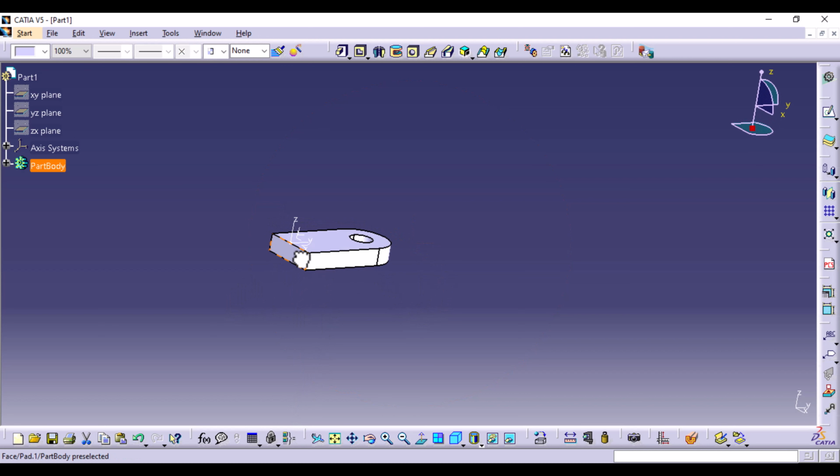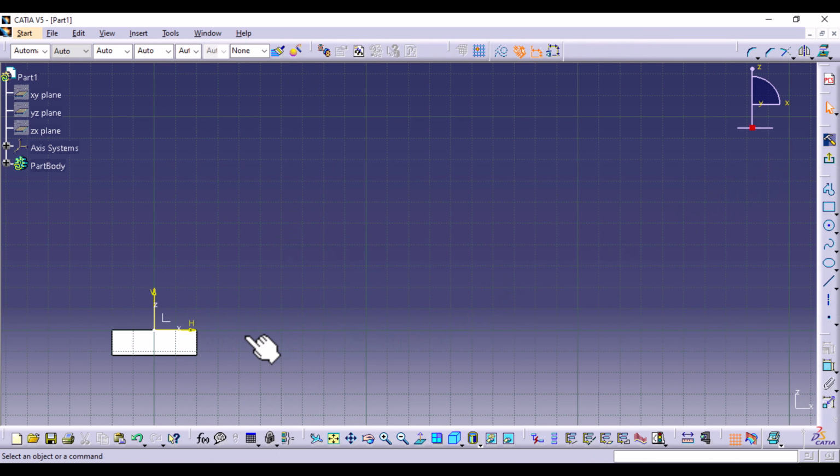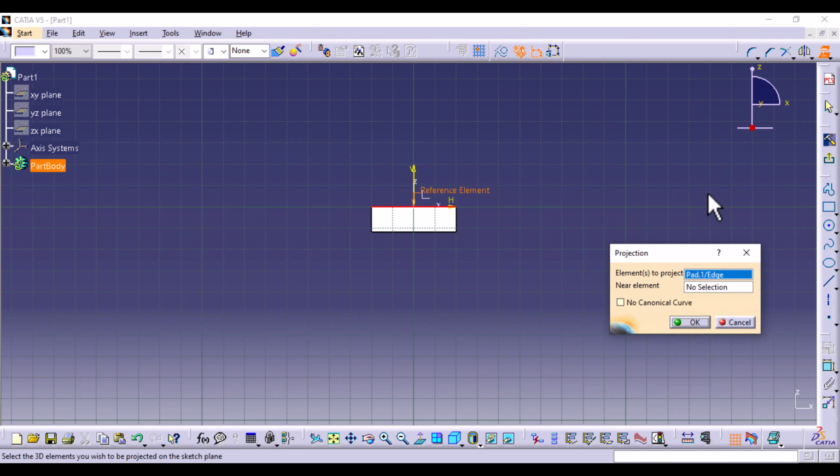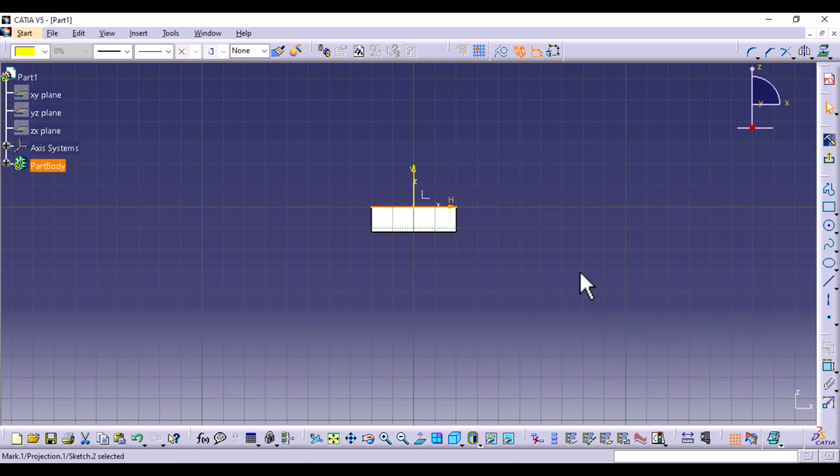We're going to create now the other face that's going down, and you can just click on this face and select Sketch. Alternatively, you can click on this plane. Let's just sketch on the face. We're going to reuse this edge. So select the edge, go to Project 3D Elements, and select OK. We're going to use it not as a construction element, but as a standard element.